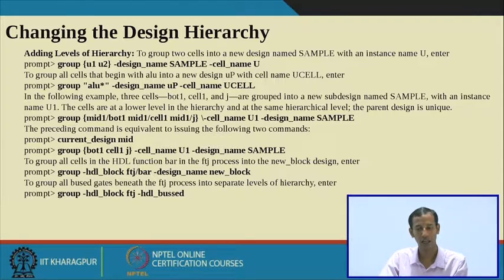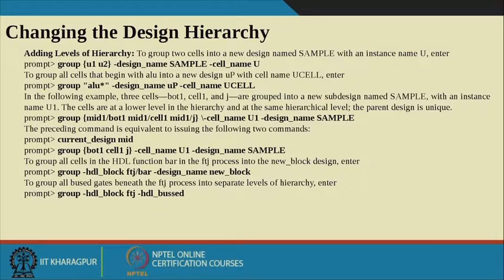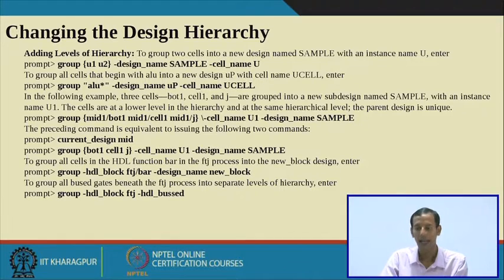So ALU star means all the cells which are related to ALU. That will now be grouped within the design name, in the design name my microprocessor, with the cell name of u cell. Okay.